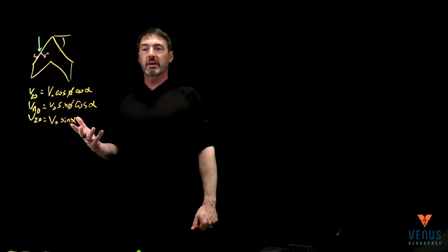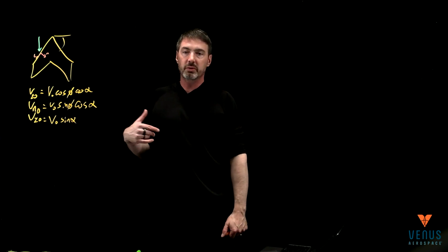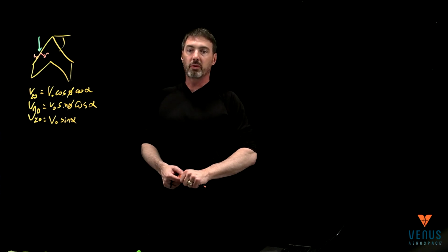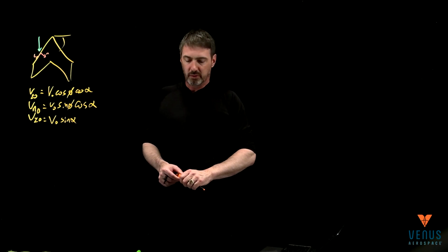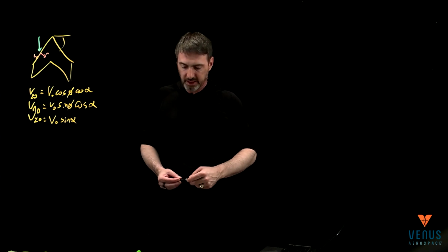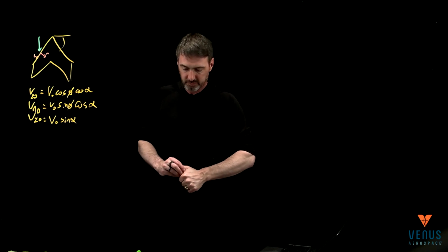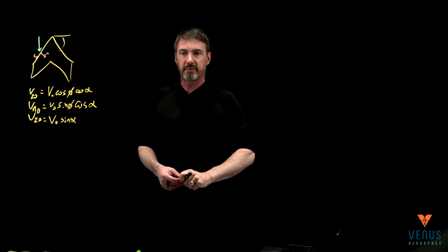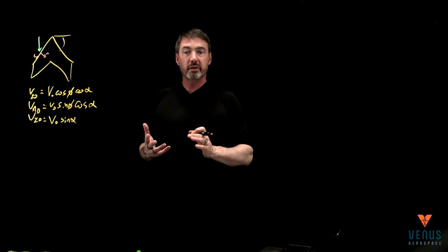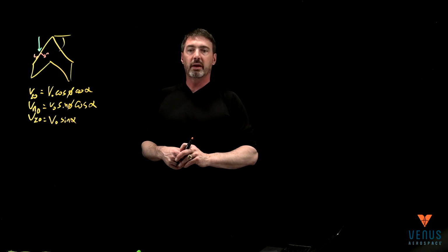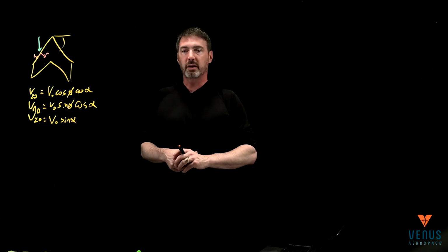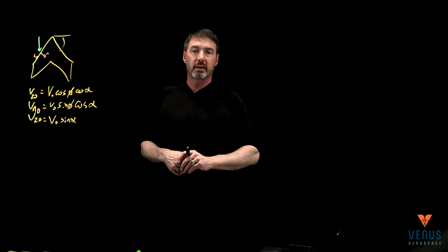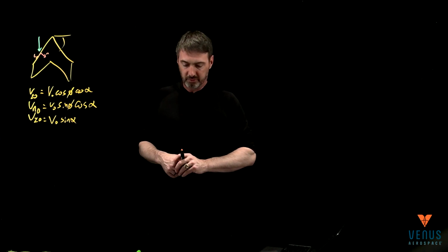So the first thing that's going to happen with the wing sweep is it's going to reduce the flow at the normal direction. And that's the main driver of ultimately the effect of wing sweep. It's reducing the speed. When you think of transonic airfoils, which we'll draw and discuss later, ultimately it's pushing back the transition to the supersonic.